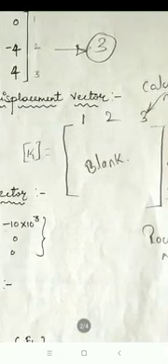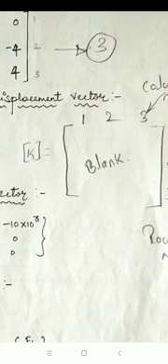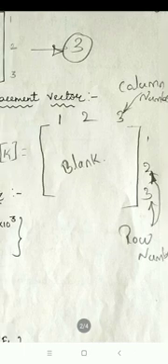Now, finding the global stiffness matrix is one of the important steps. To find that, first I will write a matrix keeping it blank. Inside I will not write anything, only the common term 10 to the power of 6, and a square bracket. I have not written the 10 to the power of 6 here, that is missing, you have to write it. And write the column and row numbers.